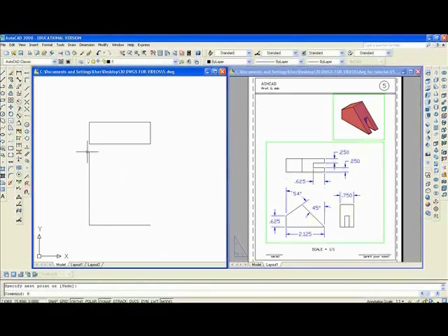I want to rotate. RO enter. L enter. The last thing I drew. I'm going to rotate it from its base point. To go clockwise, it's minus 5,4, enter. I'll draw another line from this point up. Doesn't matter how high.